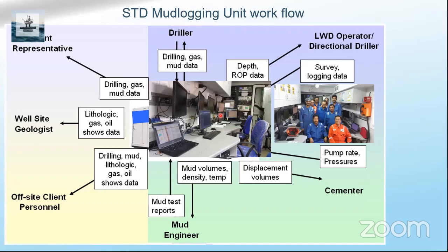And you can just have a look. Anything abnormal, as I mentioned, you can call the rig floor, the driller, and inform the drilling supervisor that, for example, the standpipe pressure is shooting up, or there is a decrease in the pressure. Could be any reason. You don't have to analyze first, but the mud loggers have to tell first, saying this, then investigation follows. So this is the thumb rule.